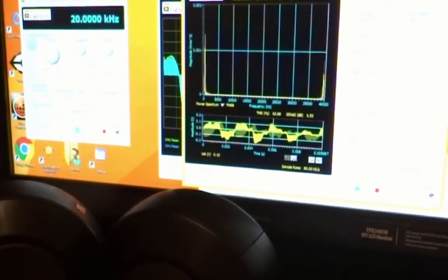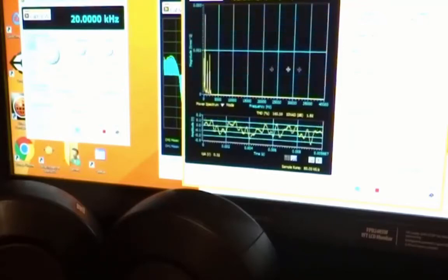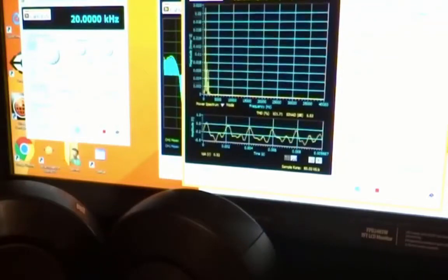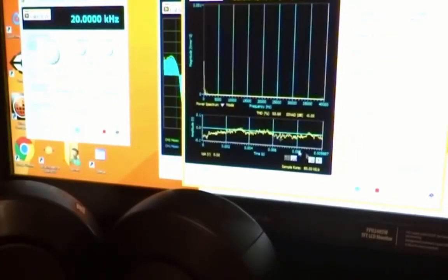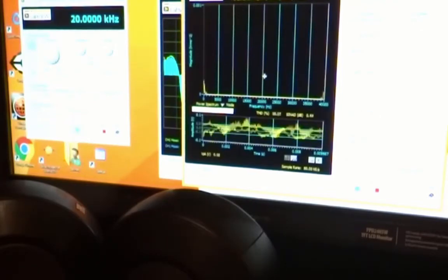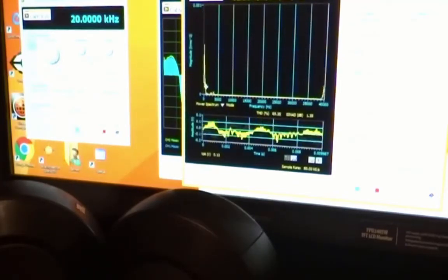So now, I put this on I1, so this is the original signal going in to the modulator, so this is the pure signal. But what we're listening to is actually this. So we're hearing this. There is another copy up at 40 kilohertz. Remember, the modulation process took this from 0 to 20 kilohertz, and then the demodulation process, the way it's implemented here, is basically just multiplying by another cosine. So when that happens, the copy at 20 kilohertz comes back down to DC, which is what we're listening to. But then another copy winds up at 40 kilohertz.